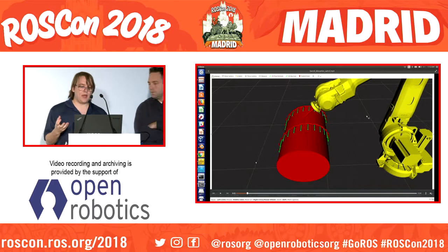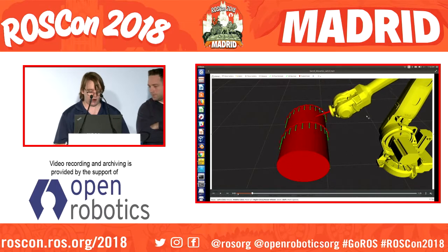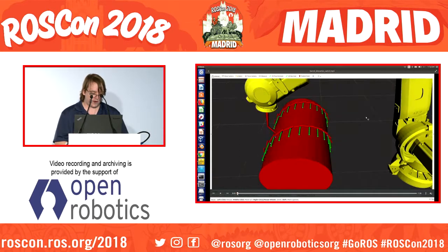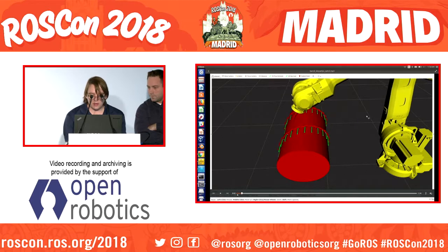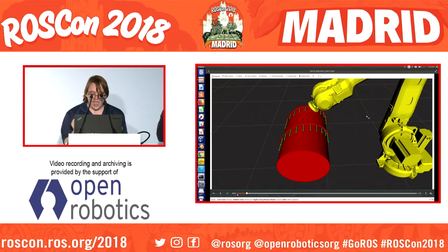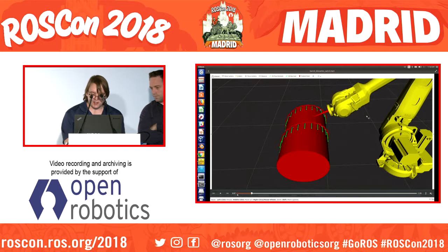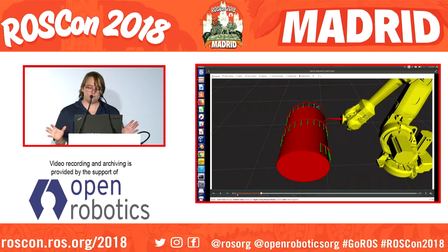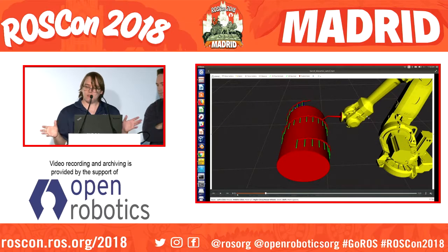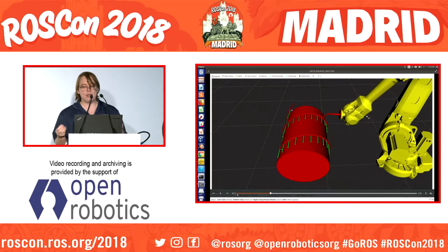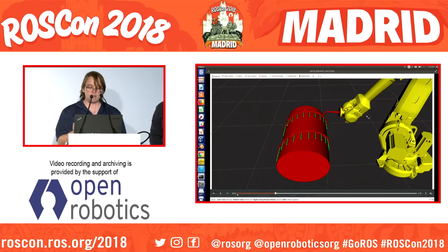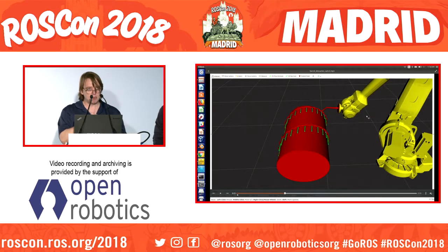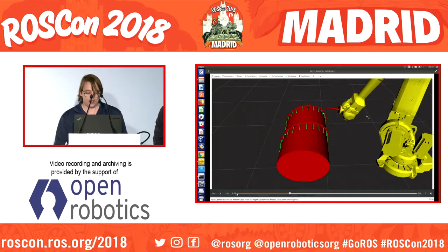Okay, so here's a plan that comes out of Descartes, right? You can see that it moves around and it does approximately the right thing. If I just highlight one thing, notice a couple things here. It's moving along, and at some point it hitches, right? And in fact, if you let it keep going, it'll just stop here and hold it still. You may say, okay, that's reasonable. What ends up happening in reality, though, is that these accelerations cause all kinds of problems when you're actually trying to be extremely fine, like sub-millimeter in your accuracy in placing things.